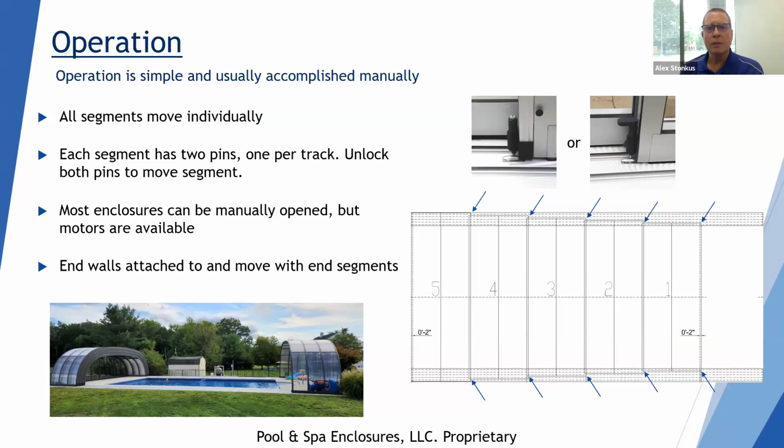We have a three-pin positioning, which means that there's a plate, as you see where the lock is. As the enclosure pin is all the way in the up position, it'll slide past that plate. If it's in the center position, it will slide and automatically lock into that spot where the enclosure is supposed to be locked down against high winds, and then just push that pin down into the ground, or through the track, and that would prevent it against high winds.